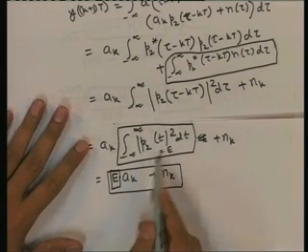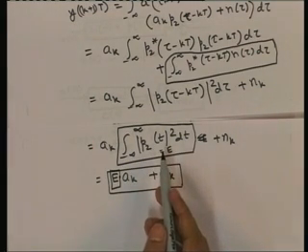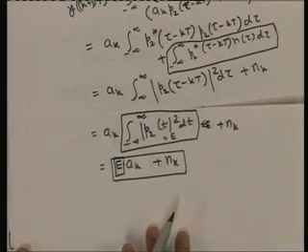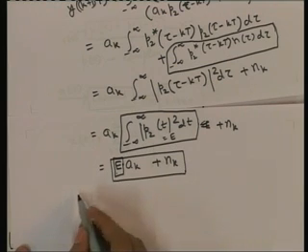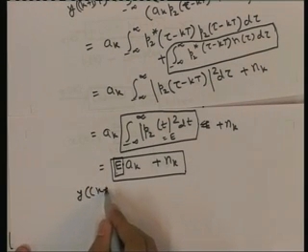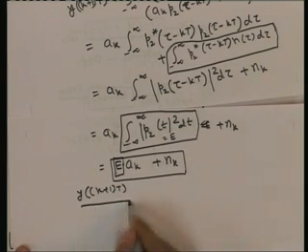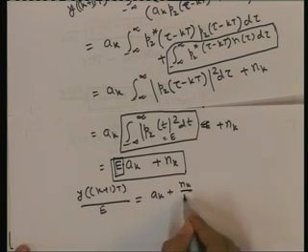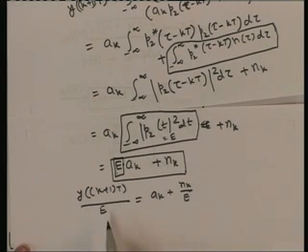So, now E is fixed. We can compute the energy of P2(t) beforehand, because we will know the channel impulse response c(t), and we will know P1(t) that we are using for PAM. We take the convolution and that is our P2(t). We can compute the energy of P2(t). So, E we know. So now we can divide. y((k+1)T) we divide by E, and we get AK plus Nk by E. So, we sample and then divide by E, then we get AK plus some noise.